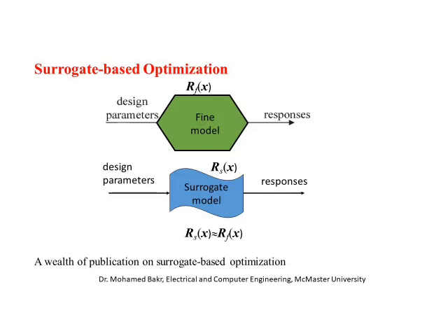Hello, in the first video about space mapping, we discussed two of the basic algorithms. The original space mapping algorithm, which utilizes two sets of points in the coarse and fine spaces to get the mapping. And the other one is the aggressive space mapping, which uses Broyden's formula and a Taylor-based step to predict the changes happening in the fine model parameters.